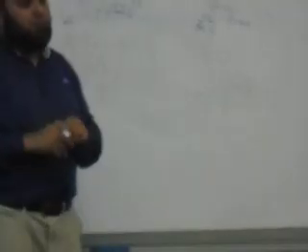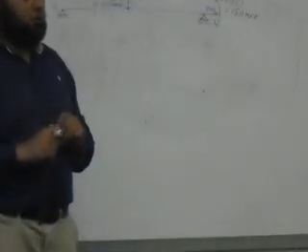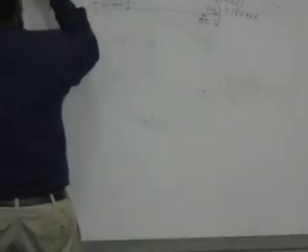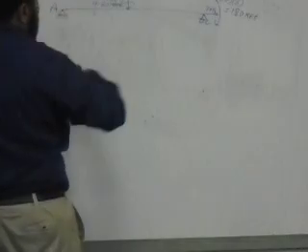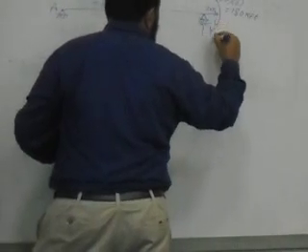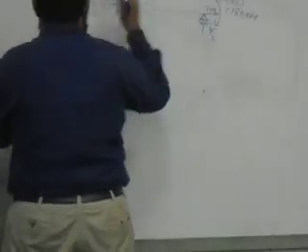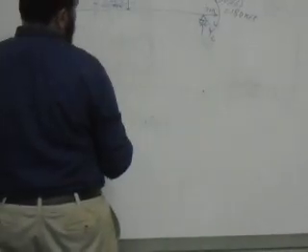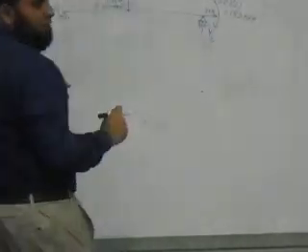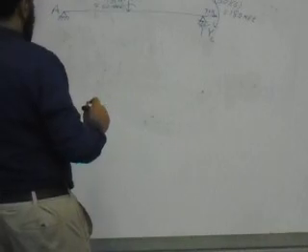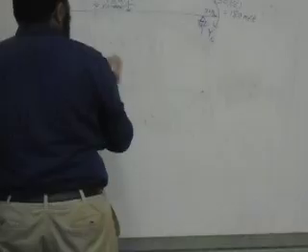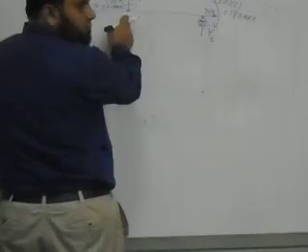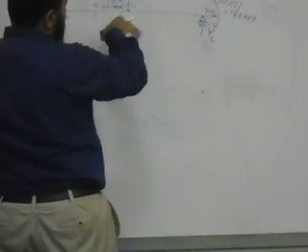But they will affect the values of my reactions, do you agree? If I take sigma moment about A equals 0, I'm getting the reactions, to get YC. I'll have 20 times 1, let's say this is the positive sign convention. The 180 kip-feet will be positive or negative? Positive, minus the 60, you agree, and the 5 will have an effect, is it positive or negative? Positive here too.